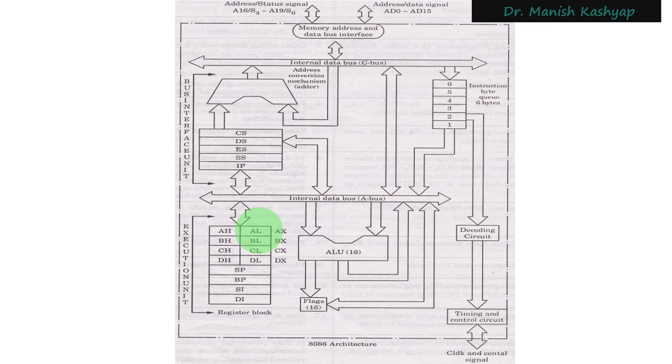So direct commands were not available in the instruction set, but here in the instruction set we will see that there are commands where AL, AH, and AX can be used as three separate entities, right? Similarly, BX, CX, and DX registers are also bifurcated into two parts. They all are of 16 bits, and half registers can also be used.